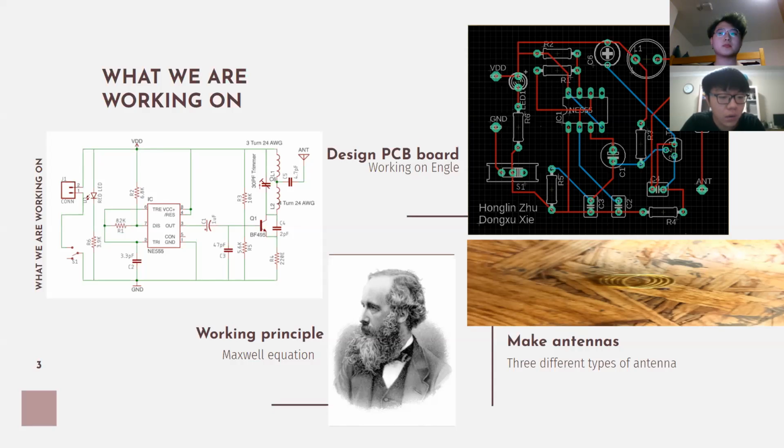The working of this circuit starts with feeding a random noise signal as the input. The signal is fed to capacitor C1 to remove the DC components in it. The signal is then fed into an RF oscillator built around a high-frequency NPN transistor T1. Besides, altering the position of the trimmer will vary the output frequency. Capacitor C4 was used to produce sustaining output frequency oscillations, and capacitor C5 was used to remove the DC components from the final output RF signal.